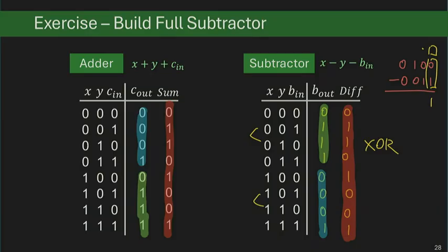How do we write it? We'll see that in 1 second. Right? You can approach it from a Boolean algebra perspective by collecting all the minterms, represent it as a sum of minterm expression, and then perform some manipulation. Or I can more conceptually think of it as having, I would say, like 2 zeros, 2 zeros. Well, not exactly. So 3 ones, 2 1. I'm trying to find the 0 and 1 pattern in that borrow out column to see if there's an intuitive way to implement it.